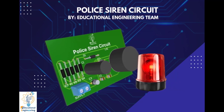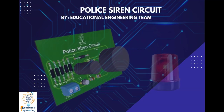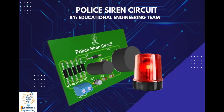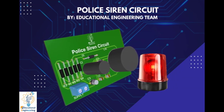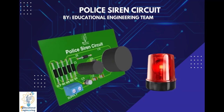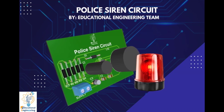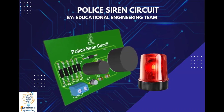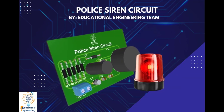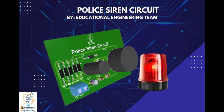In this circuit, the IC555 is wired as an astable multivibrator and it gives continuous square waves as an output. Since the output of the IC1 was given as a control voltage to the IC2, the output of IC2 will be modulated by it. Hence, this modulation action is responsible for the siren effect and the output can be fed into a speaker. Thus, it produces the siren sound. The circuit can be powered from anything between 6 to 15 DC voltage, and by connecting this output to power amplifiers, we can further increase the loudness of this siren.